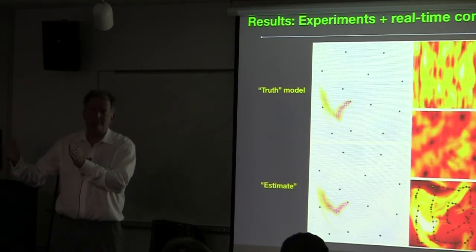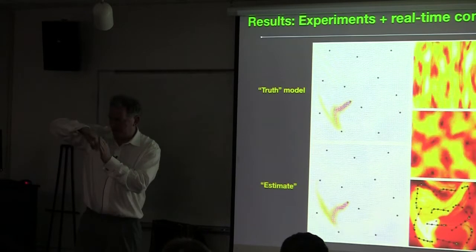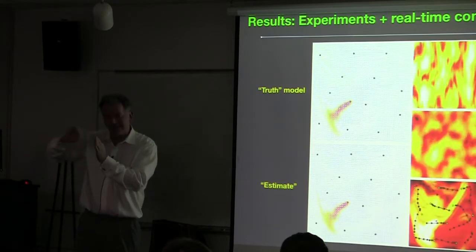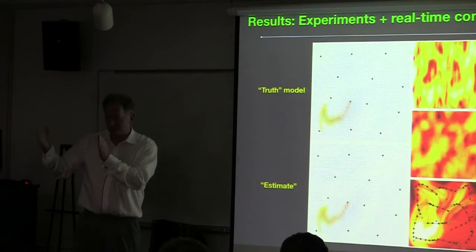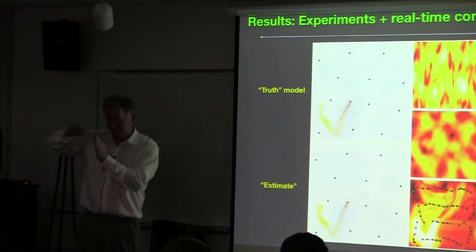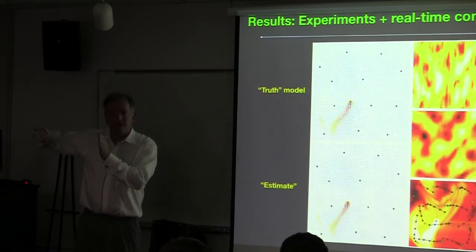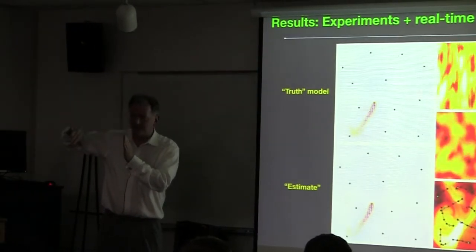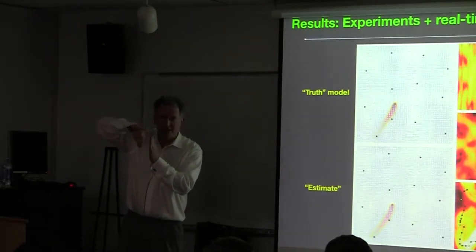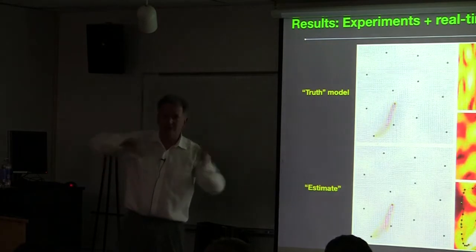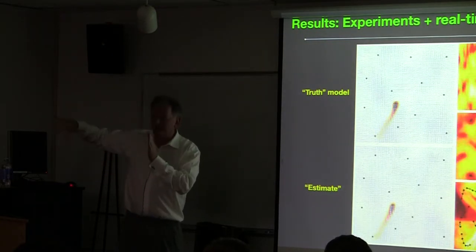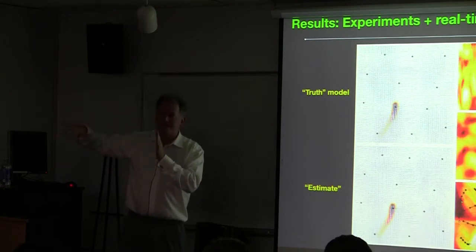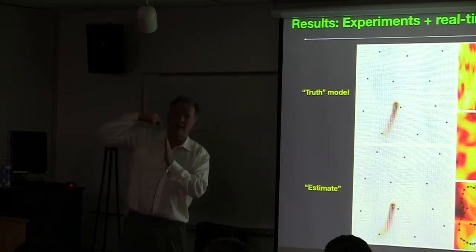And I can do that because the covariance matrix, not the estimate itself, but the covariance of the estimate, if I look in a linearized setting around my current trajectory, my current estimate of the state, the covariance matrix evolves in a way that depends upon what the C matrix is, where the sensor vehicles are, which affects the C matrix, and the observation, if you have y equals Cx, where the vehicles are affects the C matrix, but it's not dependent upon the measurements themselves.